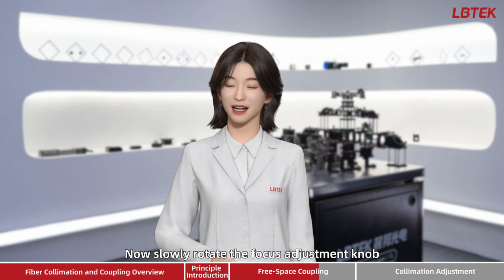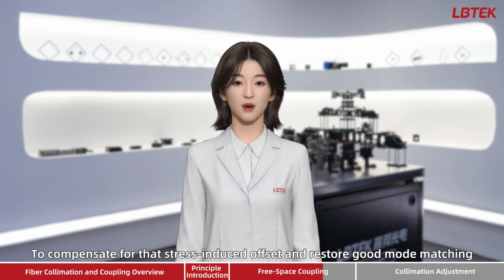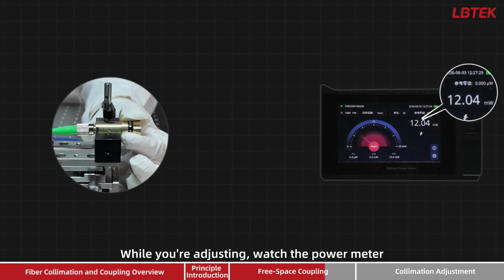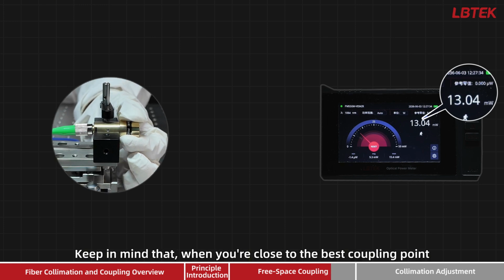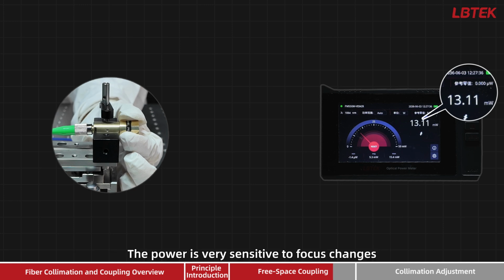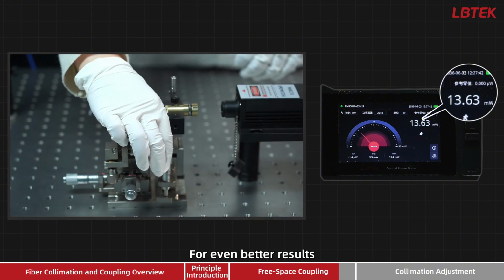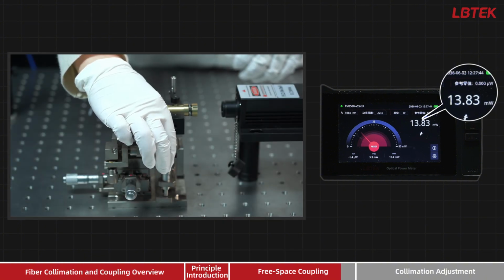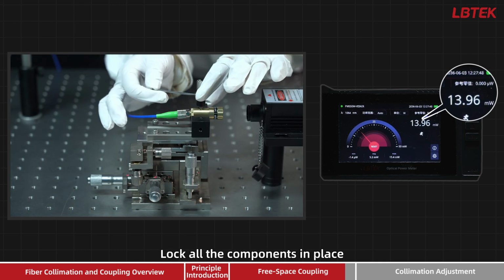Now slowly rotate the focus adjustment knob to compensate for that stress-induced offset and restore good mode matching. While you're adjusting, watch the power meter and look for the maximum reading. Keep in mind that when you're close to the best coupling point, the power is very sensitive to focus changes. So turn the knob slowly for even better results. Fine-tune the stage position. Once you find the best coupling point, lock all the components in place.